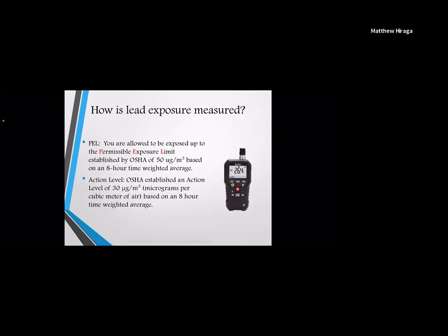And then to be a little bit more confusing, they added in that, well, here's what's considered hazardous above 40, right? And that's set by EPA. So everybody has a little dip in the regulation, but 30 tells you have to have a plan. 40 considers it dangerous. 50 is the maximum exposure with no PPE. And if you go above 50, then you better start doing some engineering controls, adding water, adding vacuums, adding negative airs, things like that. Okay?